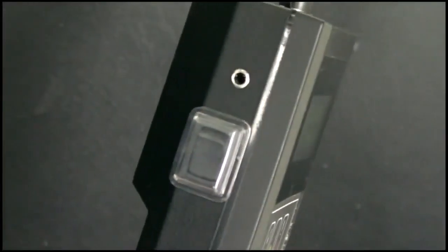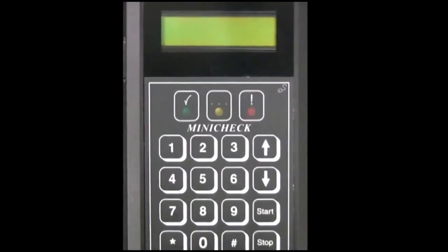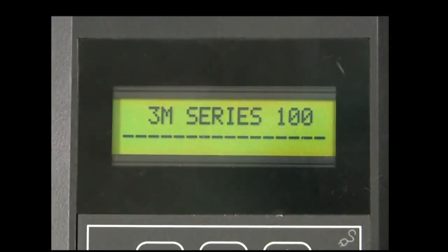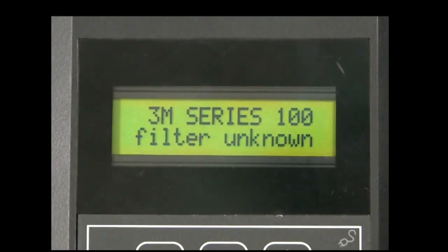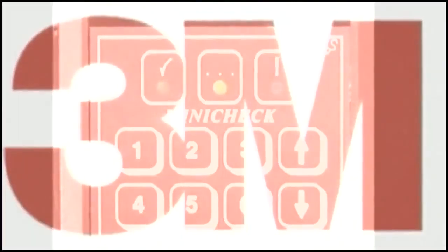The 3M Series 100 Automated Integrity Test device is activated via the button located on the left side of the device. After this button is pressed, it requires approximately 5 seconds before startup information appears on the menu screen and it's verified the device is operational. Pressing the button again prior to the startup messages appearing on the display screen will result in the device being deactivated. The service menu on the device allows the user to edit a number of parameters that will change infrequently. The most common include the date, time, language, and units of pressure displayed.